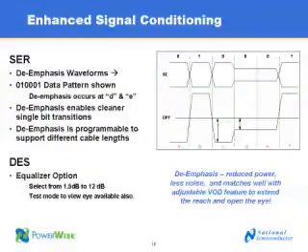Yes, definitely. We had a question that came in about the previous slide, slide 12, and the question is, what is the data rate of the serialized signal over the single pair? Okay, you're running at about 1.8 gigabits per second when you're running at the full 65 megahertz pixel clock. Yeah, and you can calculate this based on your pixel clock and knowing the fact that you're sending 28 bits in any payload. Take your pixel clock times the 28 bits, and that'll give you your data rate.